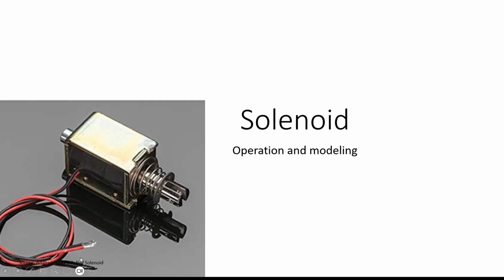And a magnet attracts iron, so the movable part of the body over here, which we call the plunger, is made of iron and/or low carbon steel as well. And attached to the plunger there is a mechanism which we want to move, of course. So when I put a voltage on the connecting wires of the solenoid, the plunger is pulled in and the mechanism moves. And to get the mechanism back to its original position when the voltage is disconnected from the solenoid, there's a spring attached over here. And that pushes the plunger back to the original position when the solenoid is unpowered.